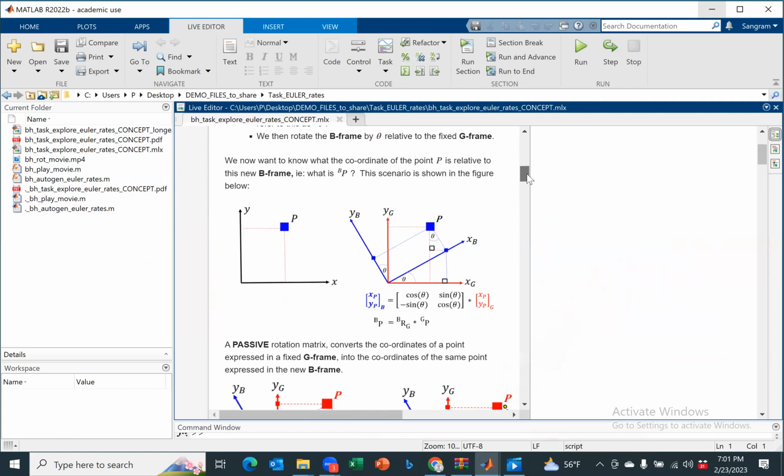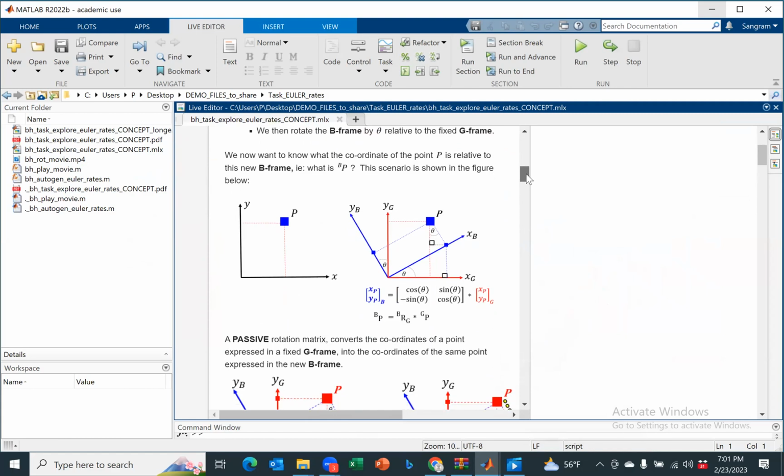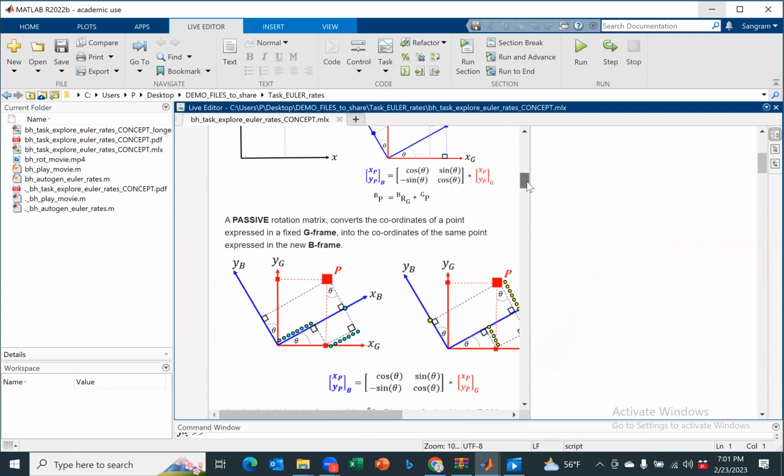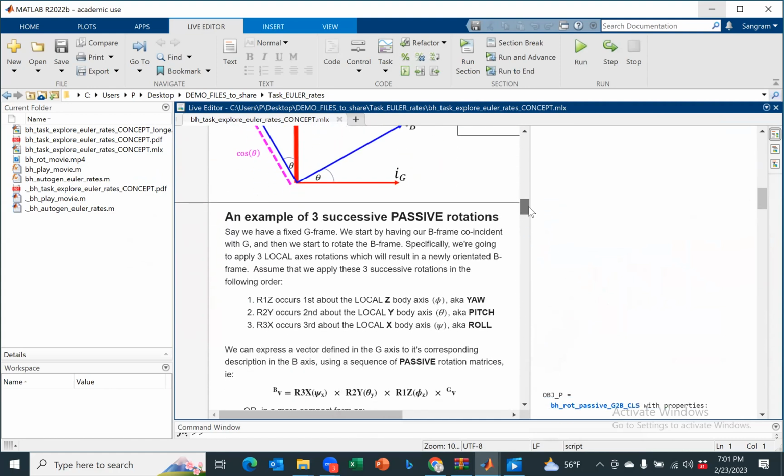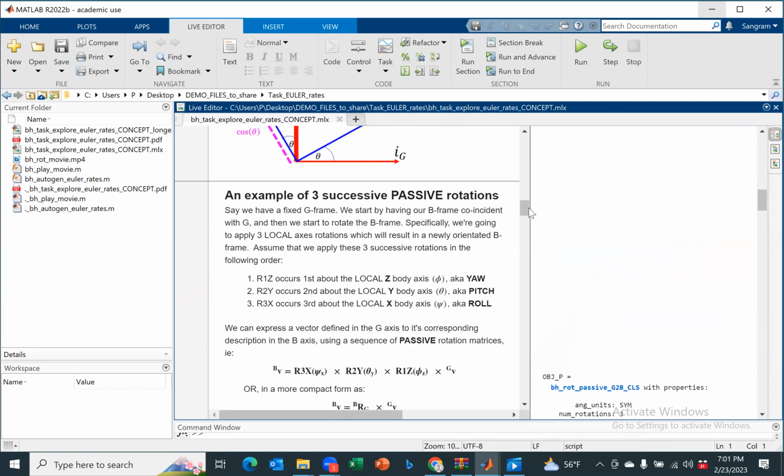Remember, this is what we did in robotics 1 when we started rotation transformation. And then these are derived. Then these are the 3 successive orientations. Remember chapter 2, we talked about this: yaw, pitch, and roll. So you have Rz, Ry, and Rx. These are the classic Euler angle triad that we use, which is ZYX. In robotics, we use this sequence ZYX.